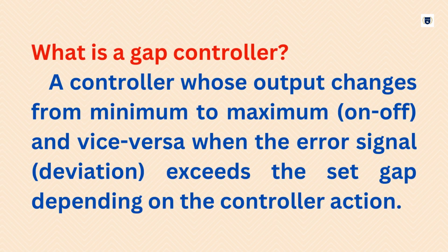What is a gap controller? A controller whose output changes from minimum to maximum, on-off, and vice versa when the error signal, deviation, exceeds the set gap depending on the controller action.